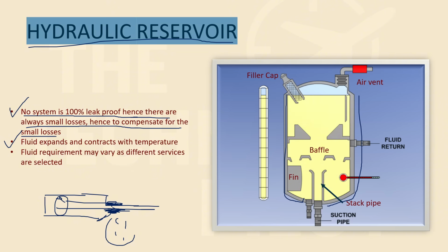Second, the fluid also expands and contracts with temperature. You might think the fluid you have here is sufficient, but as you go higher, the air is colder, and this causes the fluid to contract. So it will also reduce in volume, right? To compensate for this loss in volume, you will need some extra hydraulic fluid with you, so you can just refill it with the help of your reservoir.